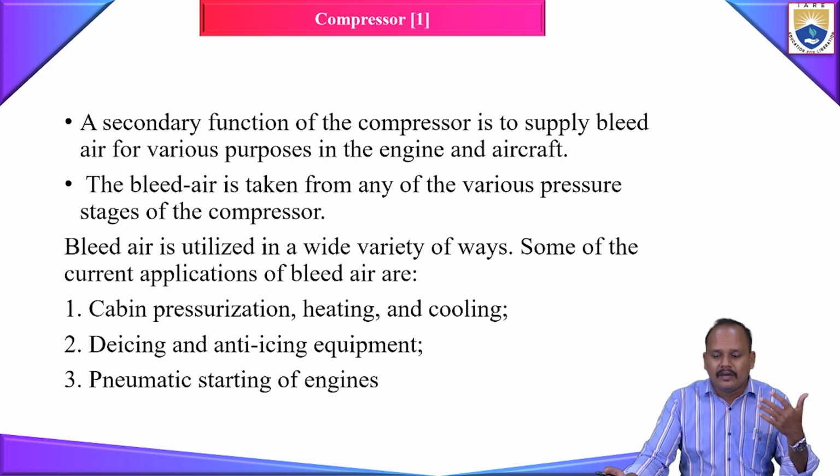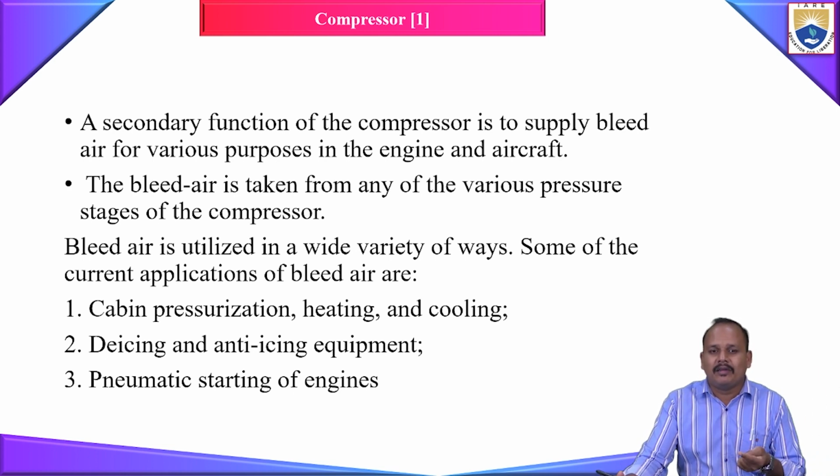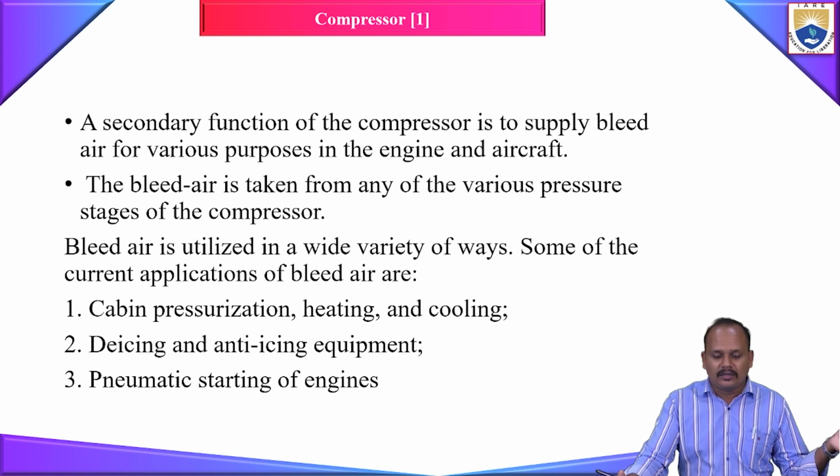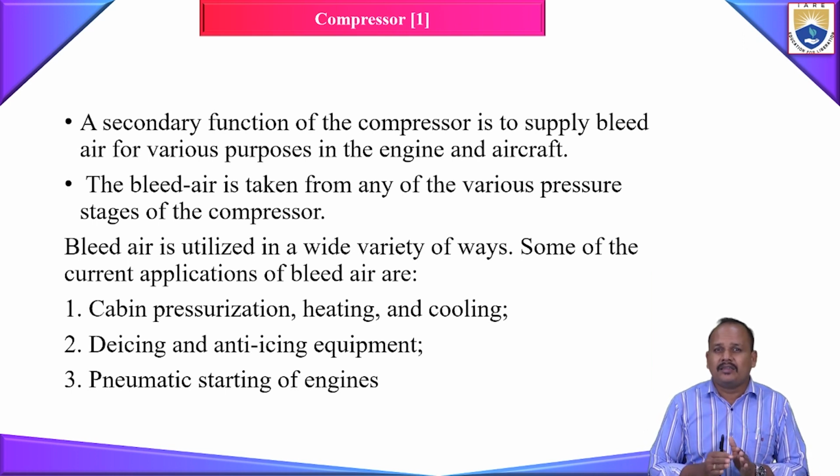So if I am going to withstand this high temperature, obviously I should provide cooling. How do I provide the cooling? The bleed air from your compressor will be passed inside the turbine blades, which is going to act as a cooler. So these are all the purposes of your bleed air. Basically, what is the source of your bleed air? It is from the high pressure stages of your compressor. So this is the function of your compressor, not only for the combustion purpose. It has multiple secondary applications. As such, the compressor in your aircraft engine is a very, very important component.